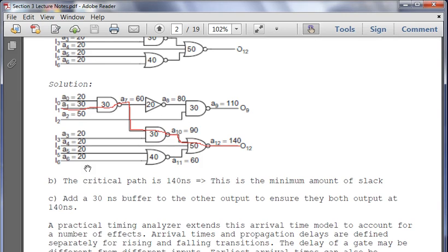For example, a 6-input AND gate is a very good example because MIPS in the single cycle data path uses 6-input AND gates for their control signals. The control signals have to be able to decide what's happening in the ALU, what's happening in the registers, and what's happening in the data memory. So if you want to design it to the CMOS level, you want to use a different type of 6-input AND gate in order to drive the circuit properly. So that's the general idea of this blurb.